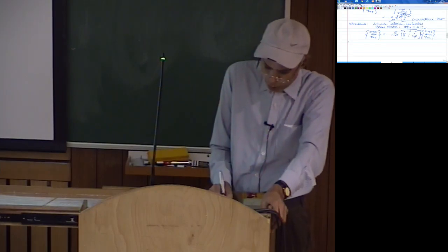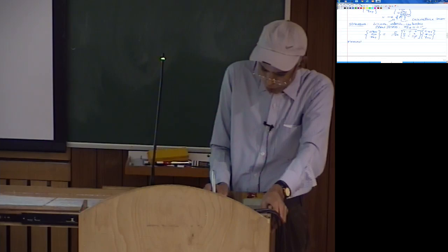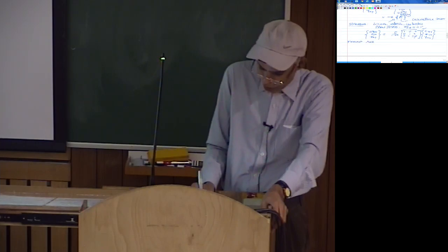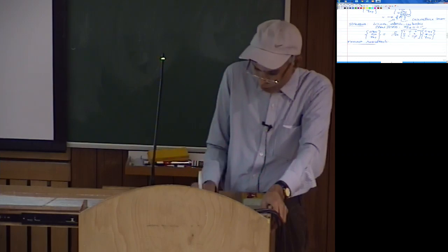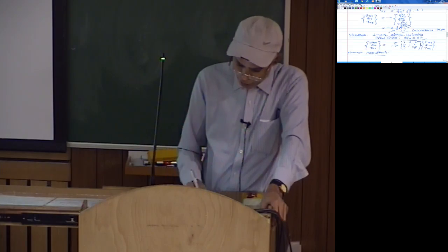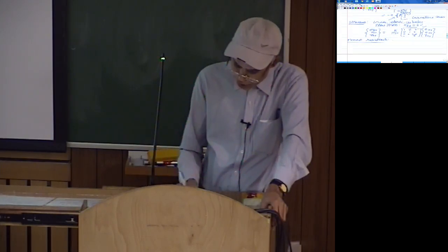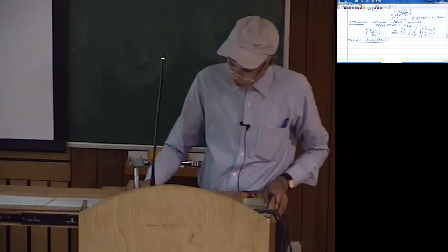moment resultants. So in addition to the stresses, we also talk here of moment resultants. These are some additional terminologies. We define moment resultants based on the integration of sigma xx, sigma yy and tau xy, basically the moment generated due to these through the thickness.